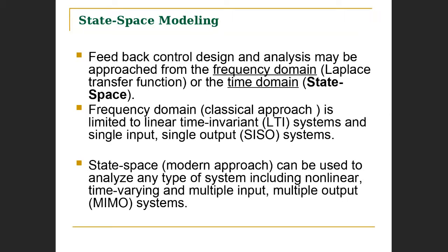So frequency domain, I will call the classical approach. It's the traditional approach. I mean, classical meaning, you know, it's a model that has been used in the early days of control system development. Right? It has its limitation. It's very simple to use, but it has its limitation in that it is limited to linear time invariant systems. That's one. And you can only model single input, single output systems, all right, SISO abbreviated.